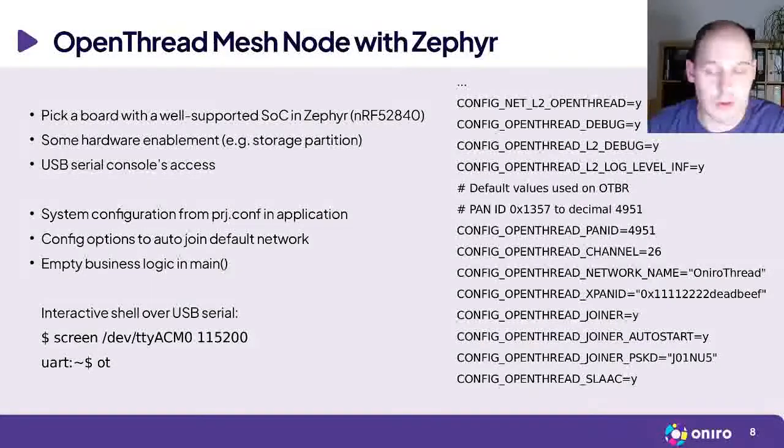And again, you could explore the system by getting a USB serial console on the device, for example with screen, and then have the OT command, which is the same as the OTCTL command you see on the Linux side. You can call help and then go explore the system.